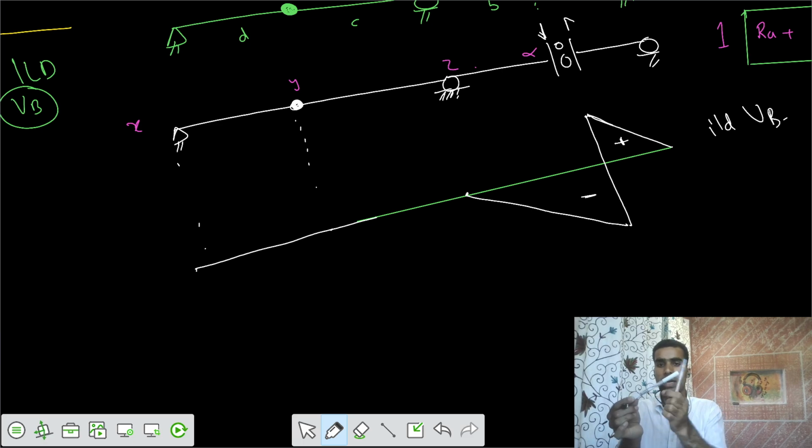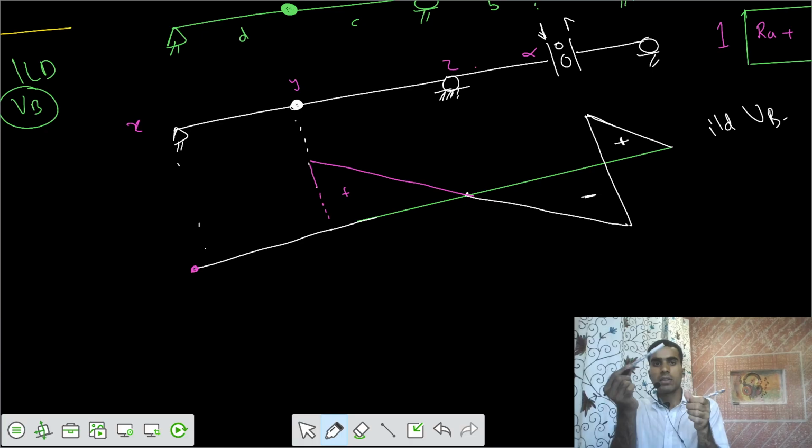With respect to the main line, z is here at the support itself. So with respect to the main line, y would go upwards. So this is our profile, that y goes upwards. So there is a variation. So this is positive. And after that, because support x won't go anywhere, once y has reached here, there we have some support x, and there we have some internal hinge also. Internal hinge can allow independent rotation of those two members. So let's say this would be the profile.